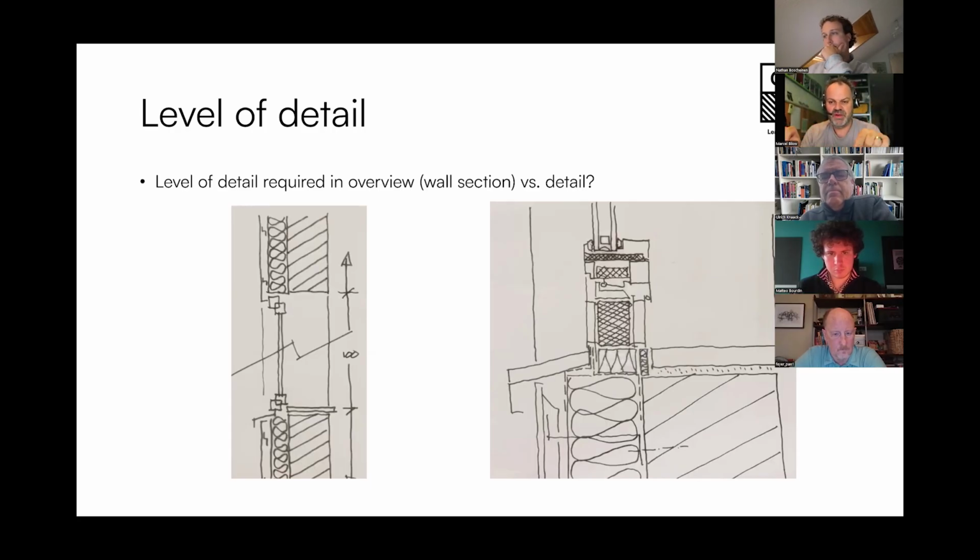measurement, and you say this measurement is 1.25 meters or 1 foot, whatsoever in American measurements, and then whatever you move and change is already within the two systems, so you can actually measure the entire window while you haven't even drawn it. Like we have here in Uli's left section, the zigzag line means there is a short piece cut out because this is just boring. You have the bottom detail and the top detail, and in the middle is just 1.20 meter glass. You don't need to show that.